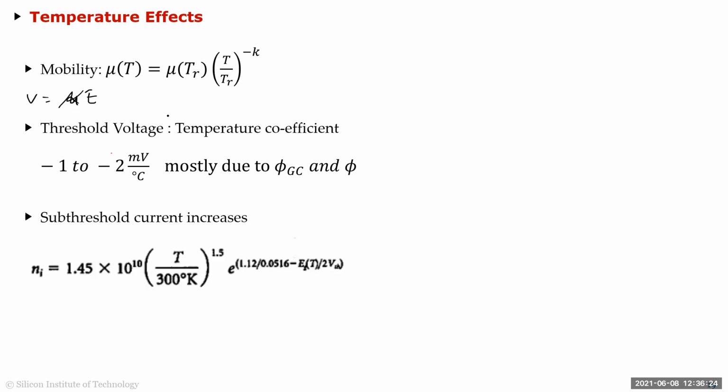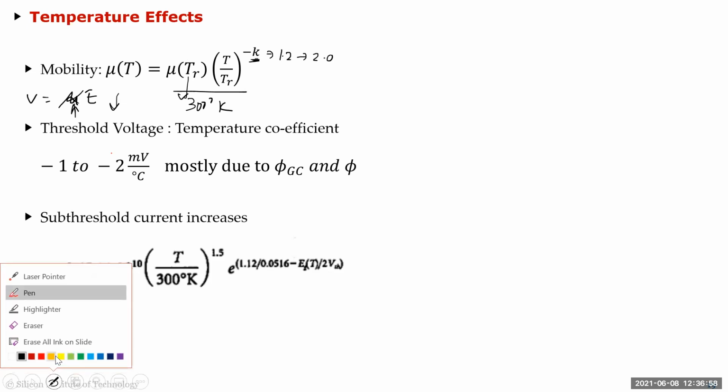So in other words, the constant we measure drops with temperature, and that's typically given by this equation over here, where TR is your reference temperature, typically about 300 degrees K. So it's whatever the mu is at 300 K, then T over TR raised to minus this constant, and this constant is usually 1.222, depending on the type of material and how you fabricate it and so on.